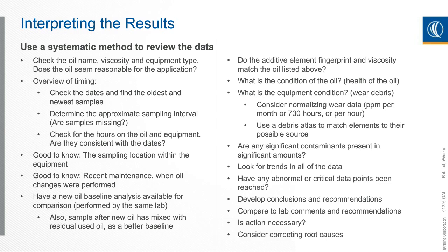Have a new oil baseline. Of course, I've mentioned that several times. It's very important to be able to know what the new oil should look like so you can know whether or not this used oil, this in-service oil sample, is quite different or not. Does the additive element's fingerprint and viscosity match up to the oil listed above? That's looking back again at the baseline.